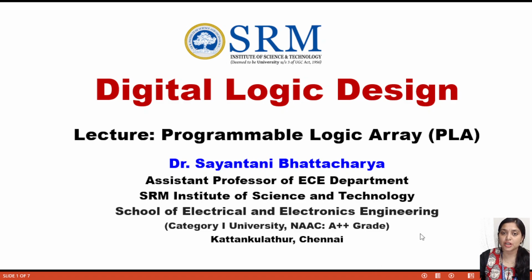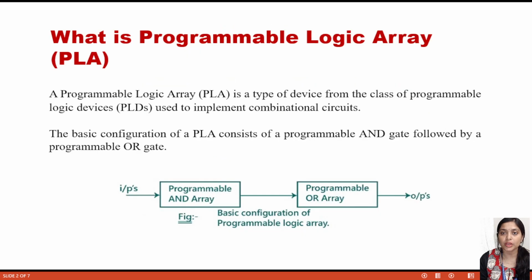Today I am going to start a new topic of digital logic design: programmable logic array, or in short, PLA. Okay, so what is PLA? PLA is a type of device from the class of programmable logic device used to implement combinational circuits. The basic configuration of PLA consists of programmable AND gate followed by a programmable OR gate.